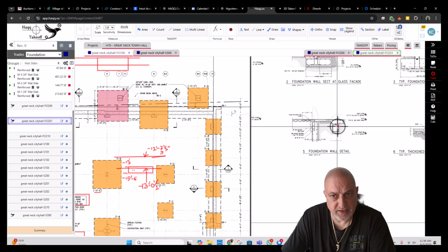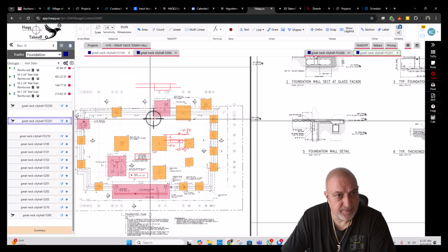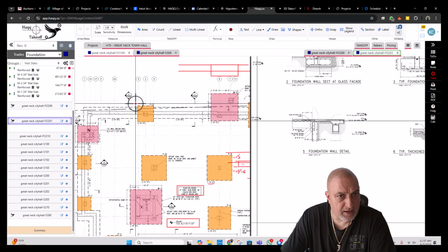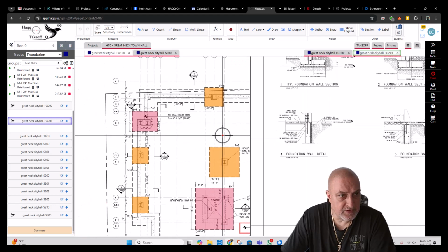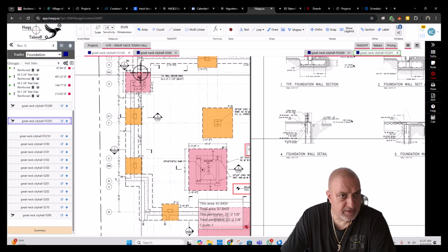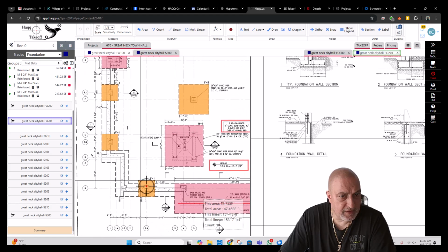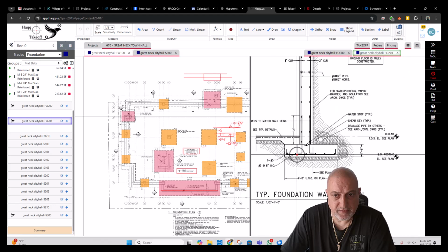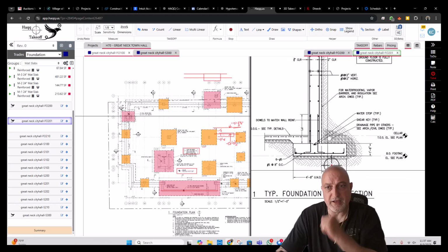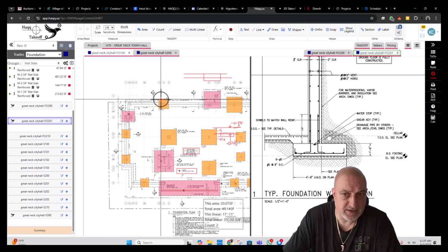See, these are the grade beams at the second level. And 1 here, 4 here. 4 is showing top elevation as well. And again, 1 and 1. So our detail is 1, which is a 4 foot 8 footing with 1 foot 6 thickness.